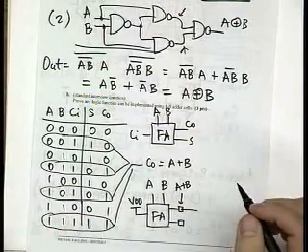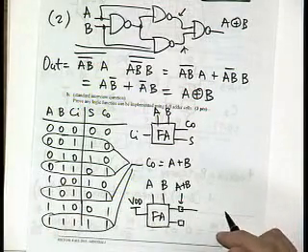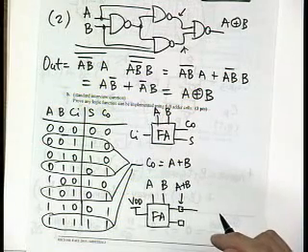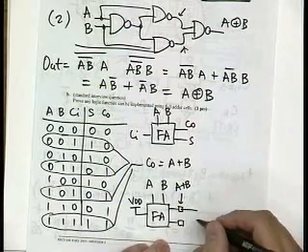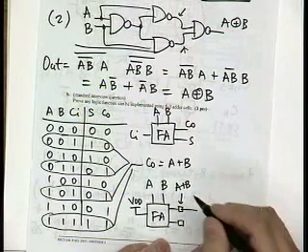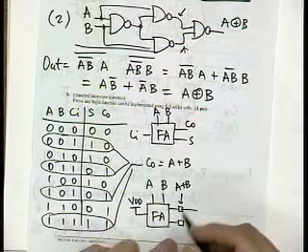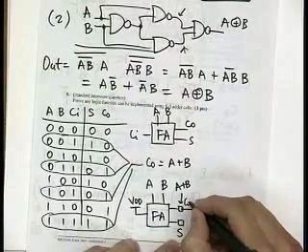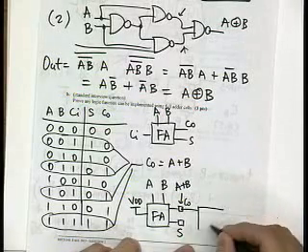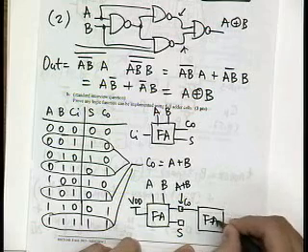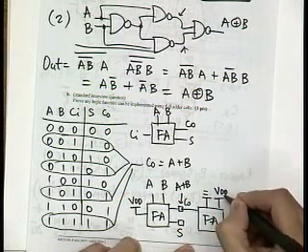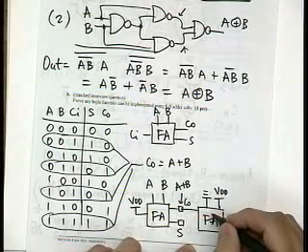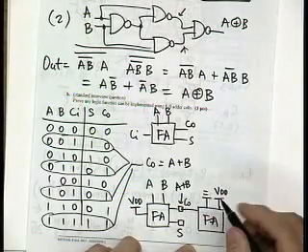So now another thing you need to do is basically implement an inverter, right? So you have a full adder, this is the sum, this is the carry out. If I feed this into the second stage where I have 0 and VDD, what this is going to do is simply invert this output at the sum bit.